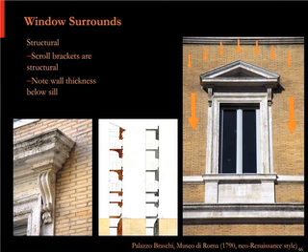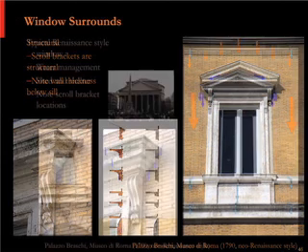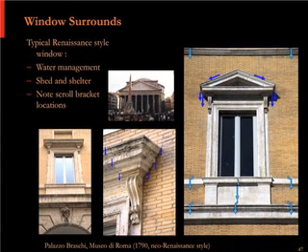Structurally, as we just talked about with the Ciciliano castle, the load is coming down from this mass masonry barrier wall. Whether you have an arch there or a lintel or a simple pediment, the load is going to be redirected around and down to the sides. So that's what we see here in the photo at the right. And that means in section, if you can see the section in the middle, the walls, as we just saw in the last photo, are going to get very thin just at that area of the floor line.